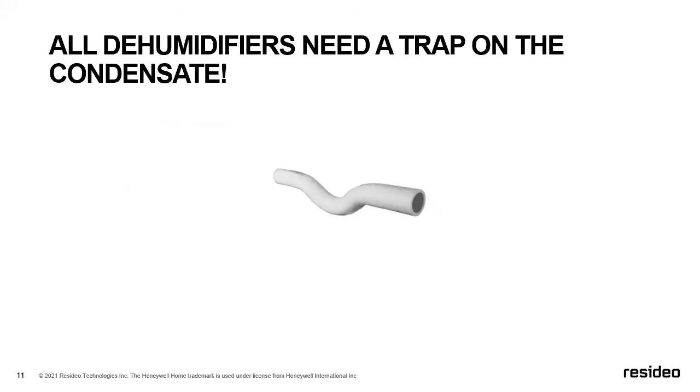Put this kind of in the beginning. One of the questions and application issues that I see pretty regularly are draining issues. Depending on how you're going to install the dehumidifier, it's really irrelevant in what you're going to do with the drain line. If you're going to tie it into maybe an existing air handling unit drain, or if it's going to be dedicated, with its own individual drain line that's going to exit the space, we need to have a P-trap on.